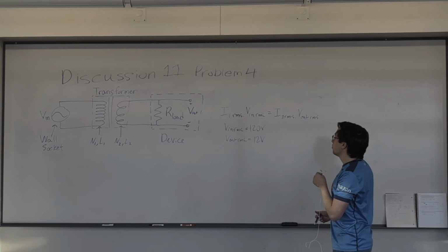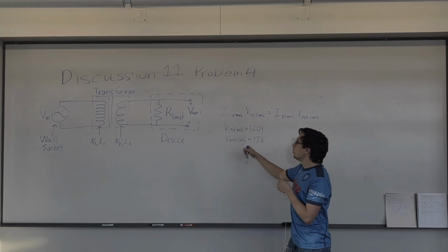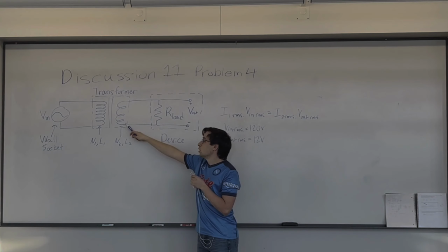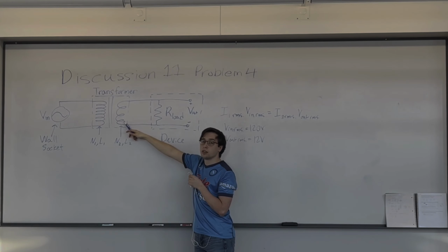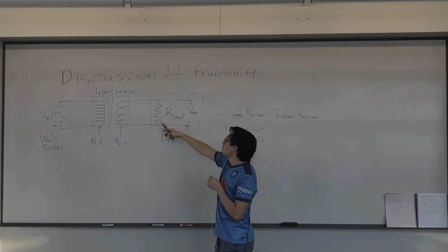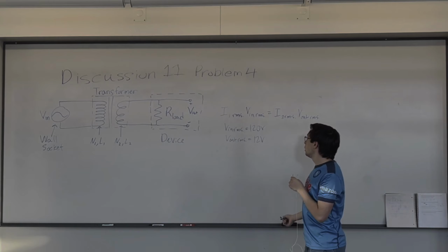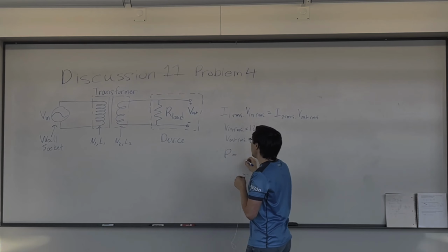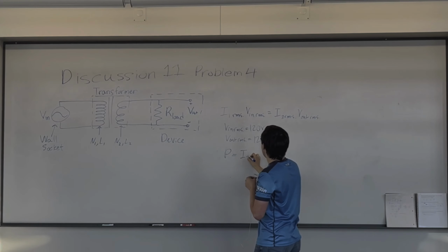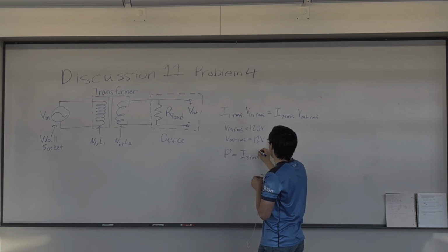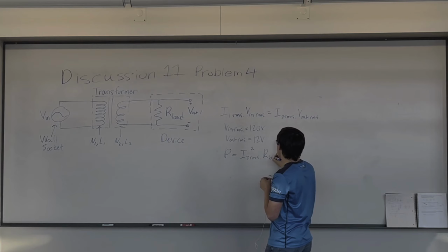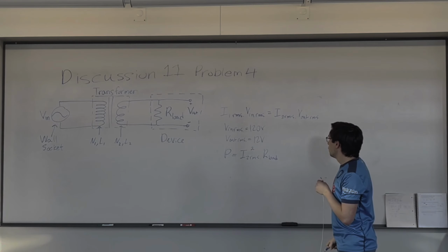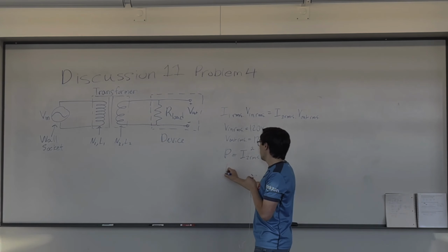And the other piece of information we want here is our R load. Specifically, whatever current is being generated in this inductor here, it's passing through this resistor, our load, and power is being dissipated in there, which is equal to our I2 RMS squared times our load resistor. Just our standard I squared R for a resistor. Okay, now our R load is 6 ohms in this problem.